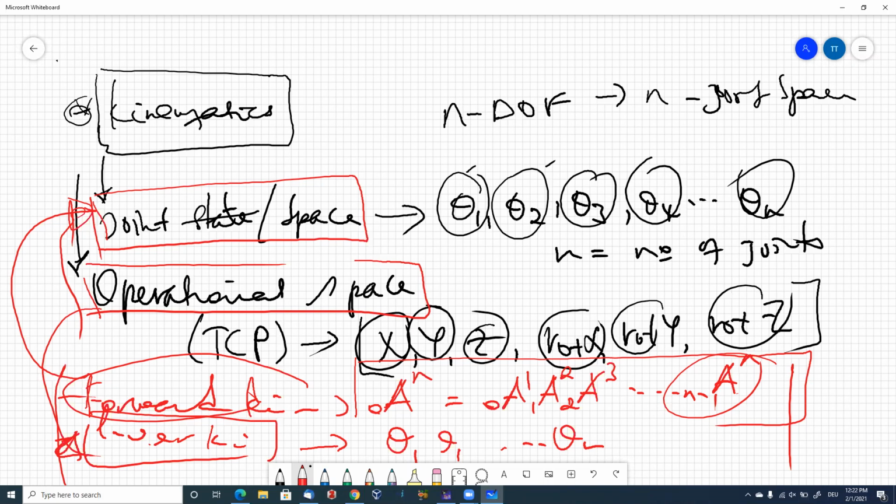And also we said that sometimes there is a possibility of having a singularity. This singularity configuration is where the robot has no solution, or where the solution is not defined. This leads the robot to some kind of confusion, where the robot will fail to decide the actual position or orientation of the robot. So we have to think about how to avoid such singularities in the space. That's what we discussed in the kinematics session.